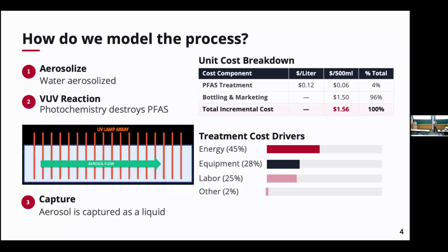We talked with a couple of different people that do similar aerosol flow. We came up with this UV lamp array, where you have a large rectangular box that you flow the aerosol through, with a bunch of lamps in there. We're targeting the same reaction time, the same residence time in the reactor for each particle of water. Higher light flux? More lamps, basically. Yes.